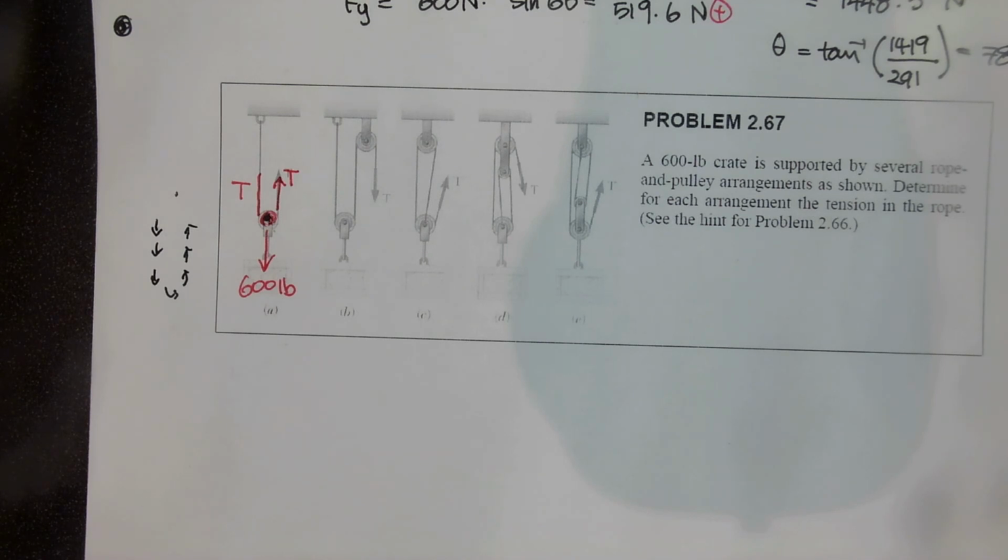So the internal force should be downward, but when we think from the perspective of this point, the cable is always pulling. That's cable tension, right? Cable compression does not exist. Cable is always pulling the opposite side of the body. So if we are thinking about this point as the point of action, then cable tension is always outward. If this is upright, then it's upward.